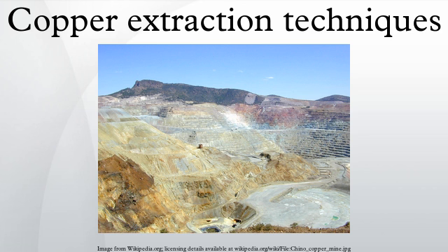Flash furnace smelting. In flash smelting, the concentrate is dispersed in an air or oxygen stream and the smelting reactions are largely completed while the mineral particles are still in flight. The reacted particles then settle in a bath at the bottom of the furnace, where they behave as does calcine in a reverberatory furnace. A slag layer forms on top of the matte layer, and they can be separated and tapped from the furnace.